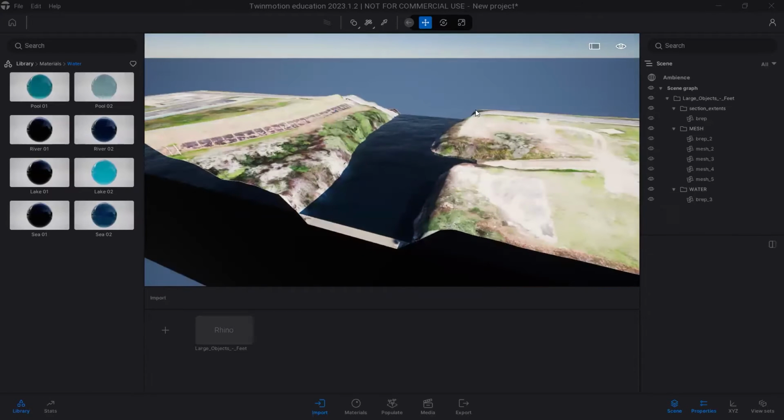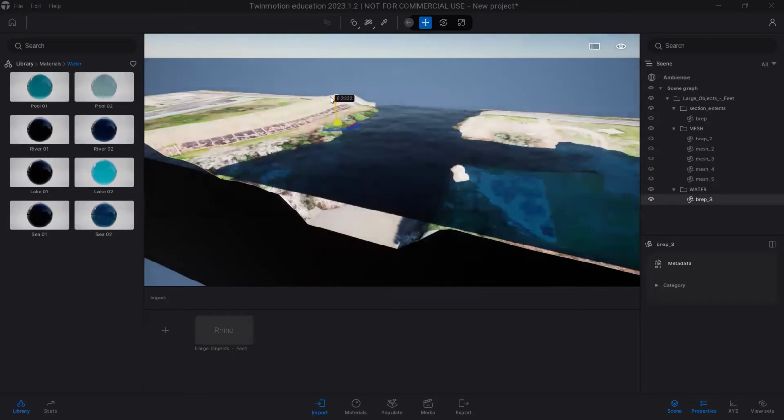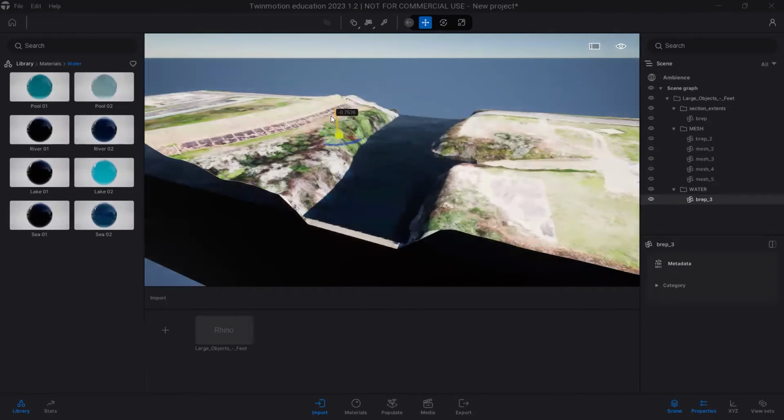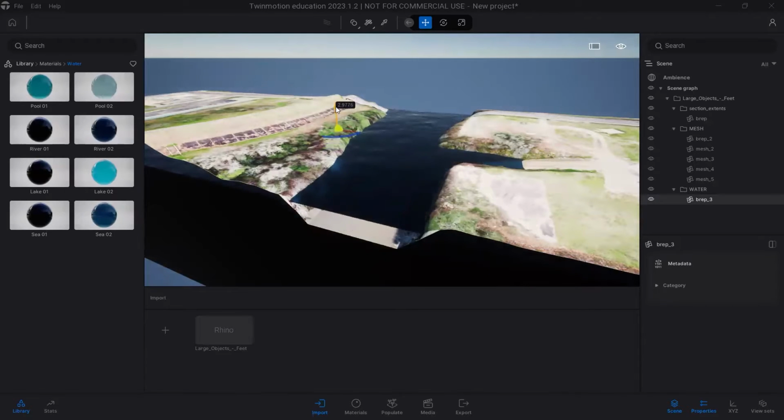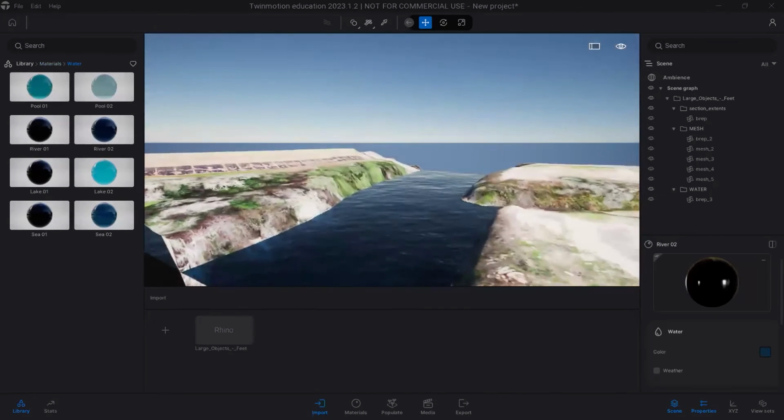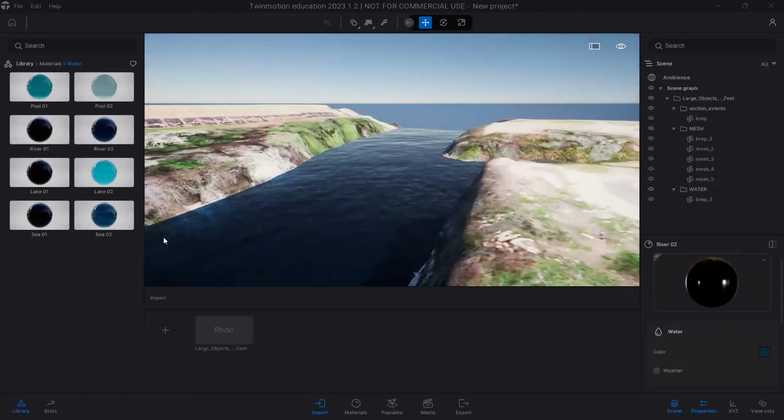One thing you can do is once you have that created, you see on the right-hand side, you have that water feature there and that B rep. You can use that to basically create a condition where you can capture a very detailed water level. So this is great when you want to create scenarios of your design that show the various flooding conditions. And now what we'll do is we'll add a little bit of vegetation onto this model here.